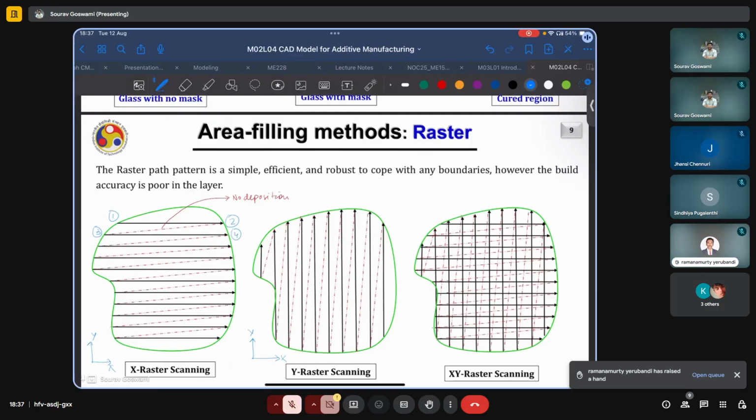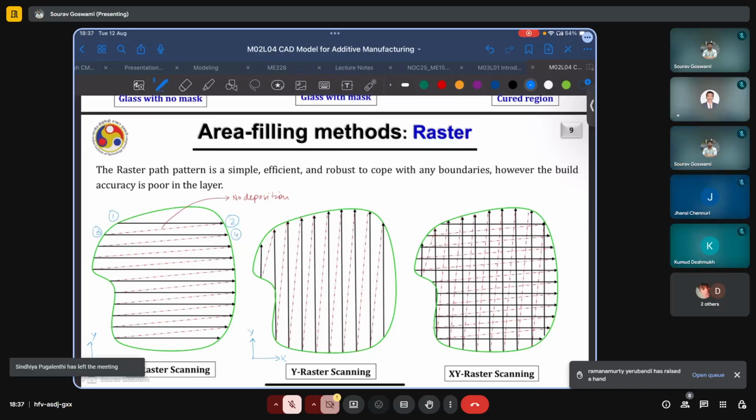Typically, this will be a rapid motion of the CNC head. And while visualizing G codes, we might also have seen that the visualization for an actual deposition path, such as going from 1 to 2, and the visualization for a path going from 2 to 3 is different. And that is because of this lift in between.